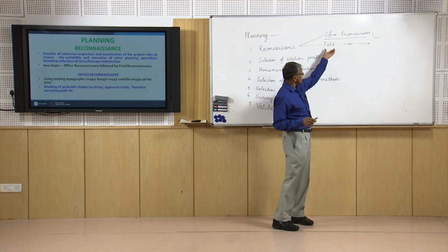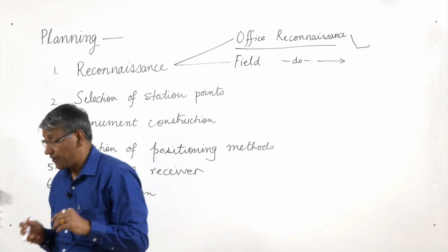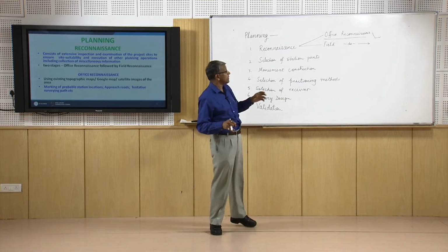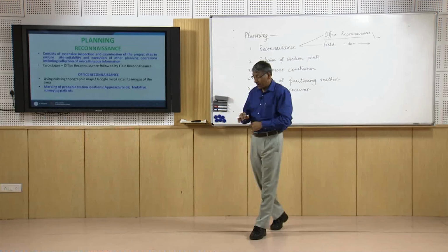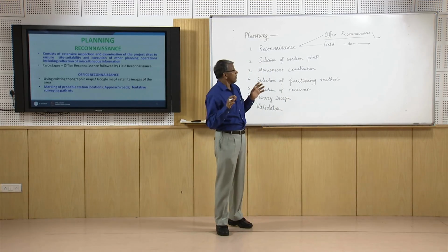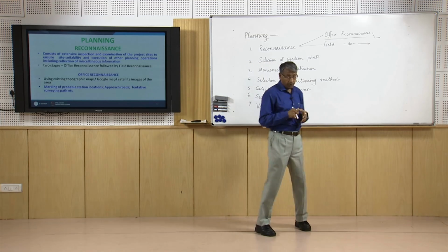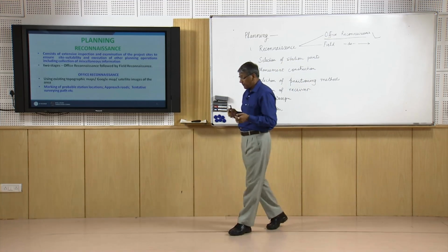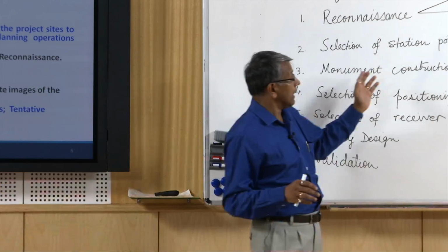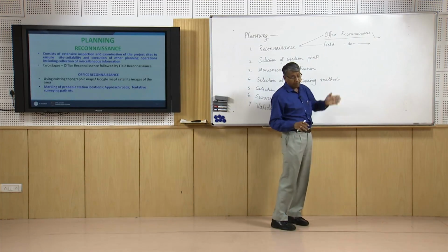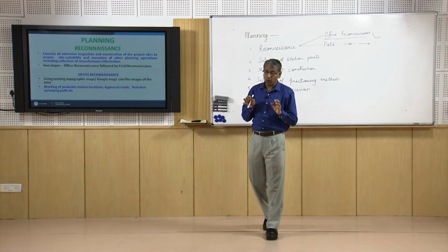Then another important point during the field reconnaissance is to check the stability of the stations, whether the location is stable or not. For long-duration GPS surveying, we need to have a permanent stable location.